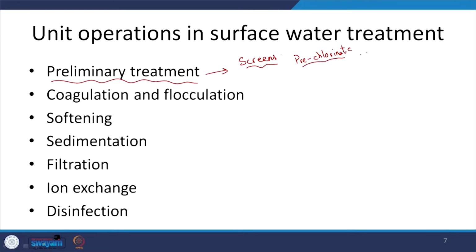Another case is when you have high iron content in your water, let us see, right, Fe2 plus or manganese or such. So, you want to precipitate that out. How do you do that? Iron in the form of Fe2 plus is very soluble, meaning it wants to stay in water. But if you oxidize it to Fe3 plus, right, so how will it go? Fe2 plus goes to Fe3 plus plus electron, right, or if you see to it that the electron is removed, then Fe3 plus will typically precipitate out as Fe(OH)3 solid pretty easily.